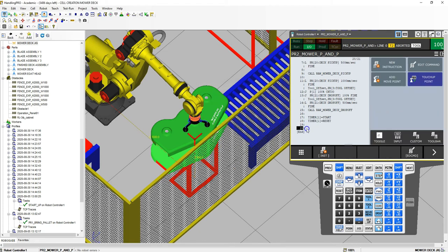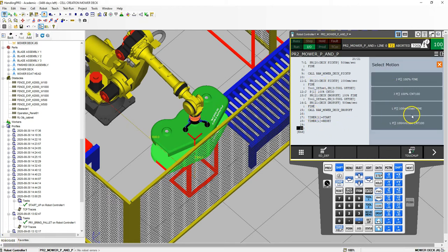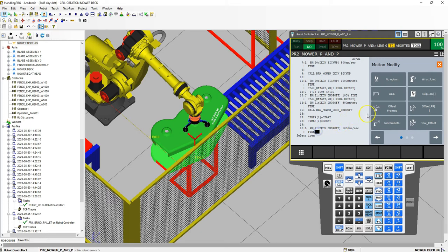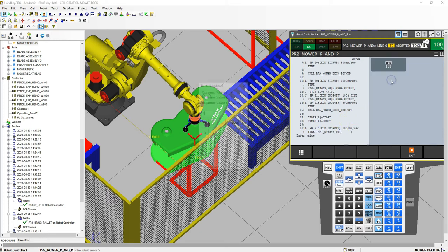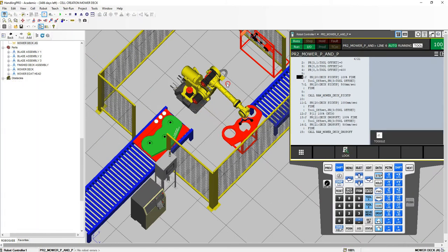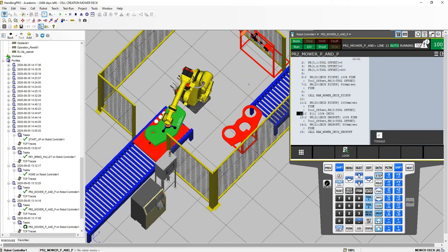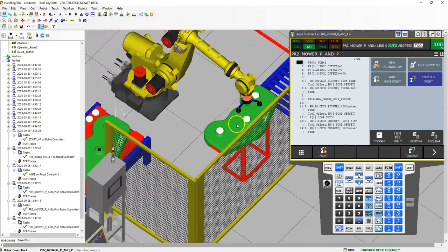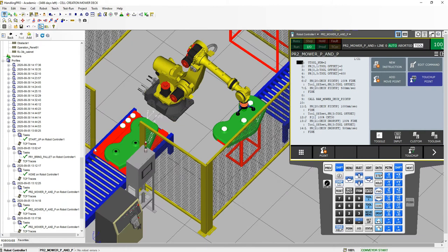So now that we reset that timer, let's move our robot arm up. So add move point, we're going linear up with no parts, so we're going to just do 1,000, and then position register number 21, which is our drop off, and then that tool offset number 3. Okay, so let's actually see this run. There we go.